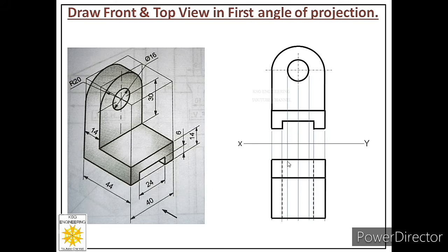So it means we will convert this projector and this projector for this width of 14 as dashed medium lines. So you can see this dash medium line is for this diametric end and this dash medium line is for this diametric end. And we have represented this hole only in this width. Fine, because hole is in 14 mm width only. So after that we will draw its center line also. Now you can see we are ready with the top view as well.